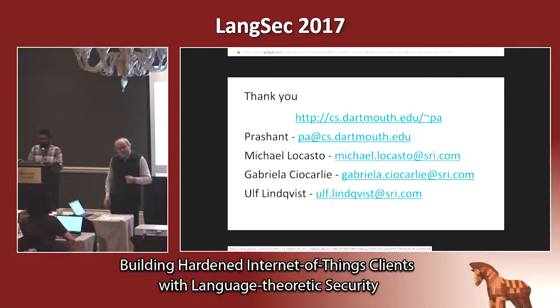I was wondering whether you have thought of applying this to protocols that are not built off of, for example Z-Wave or something. There has been work in that direction in the power grid, but not by this group specifically. But we would definitely love to look into that. Z-Wave and 802.15.4 have interesting properties. The packet-in-packet attack was found in 802.15.4 as it was for Z-Wave. It's using a two-channel scheme there, but ultimately the packet format, I believe, is the same. Fairly complex packets certainly could stand for some of that.